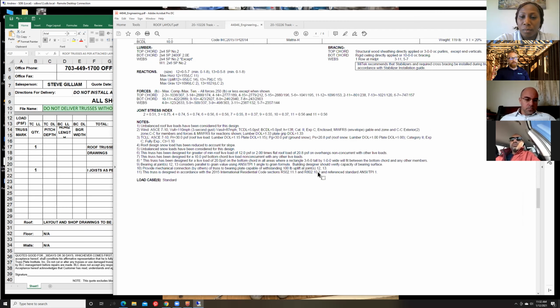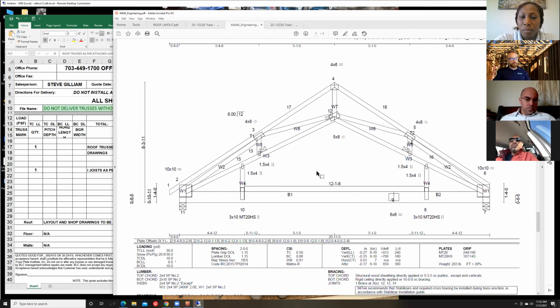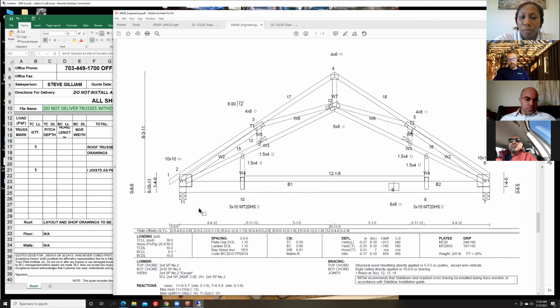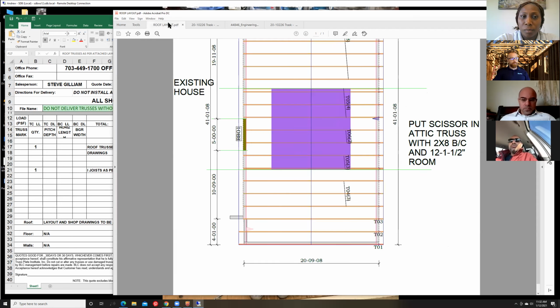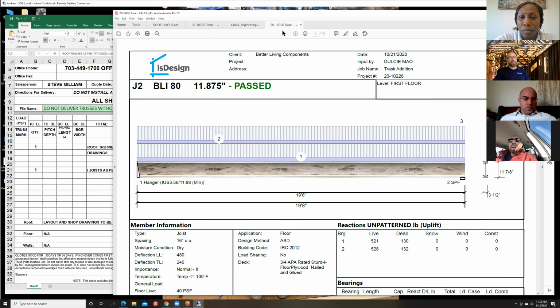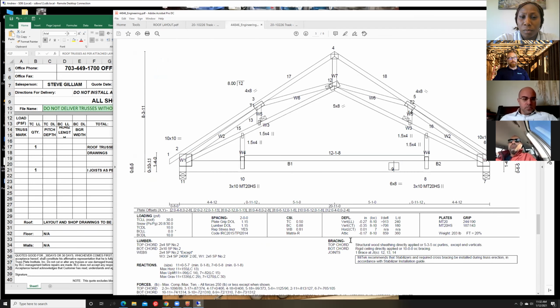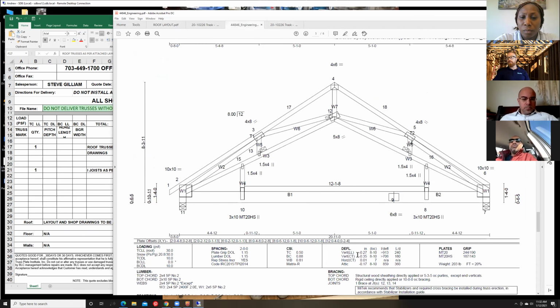So scrolling down in the middle of this layout, in the bulk of this where the purple is, we're looking at 3 different kinds of trusses. So we just want to verify that. We know that it's supposed to be a storage truss for this particular house. So they want the storage. We also know that that is not going to be a scuttle hole to get up in there. That would be a side access that's accessible from one of the scissor trusses.